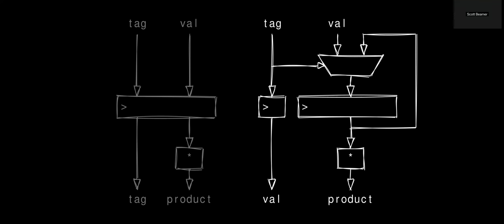Sure. I was thinking more about the sense for a designer. There's the recognition of a scenario being a don't care, and then there's the effort a designer puts into actually marking that Verilog as X, right? They can know this is effectively an X, but not bother marking it X and just turn off a write enable downstream so nothing valuable gets damaged.